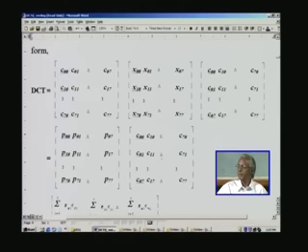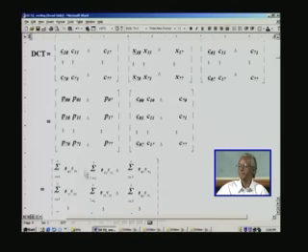So element by element, P0 into C0 plus P01 into C01 and so on. So again you require another 8 multipliers here, and one more adder is required for adding those, and when this is done, you would have got the very first DCT coefficient here. That is what is shown here, right?